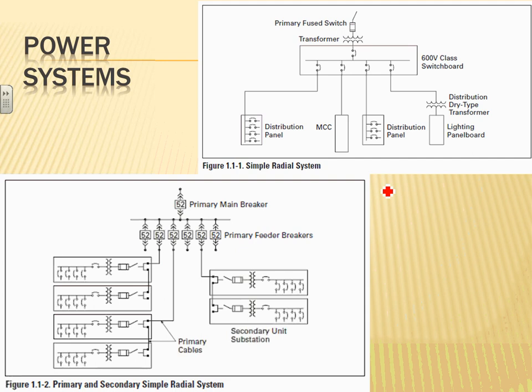What I thought, guys, to move through, just to review the power system, because when we talk about transformers, to me, a transformer is a power system. The most common, simplest and cheapest power system is the so-called single radial system. Do you do single radial? A single radial system is when you bring the power to the building, the service, with one feeder, no generator, nothing, typically, and you go with another feeder to another panel, and from the third panel, another feeder, one feeder from each panel.